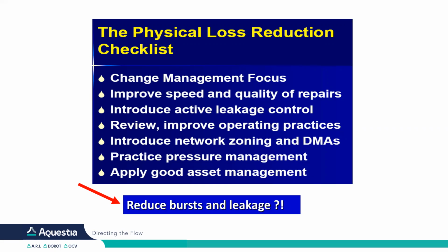But how do you reduce the bursts and leakage? That's the topic I would like to address, the linkage between the leakage and the bursts, and how you can prevent those bursts by giving good protection to your system against pressure transients, which will cause a burst in your system.